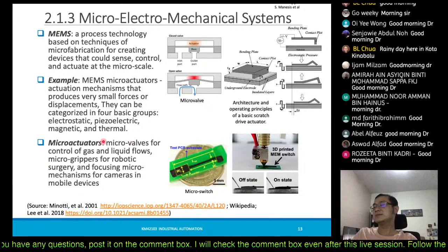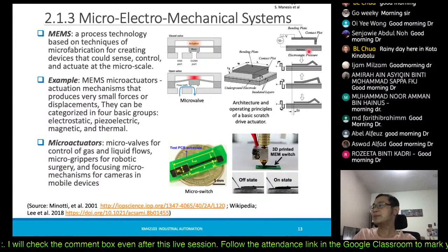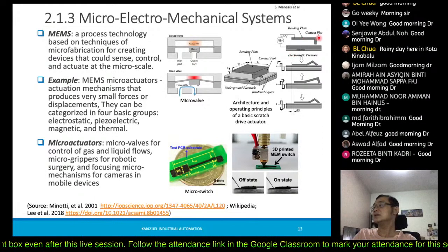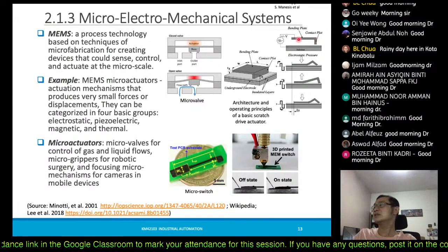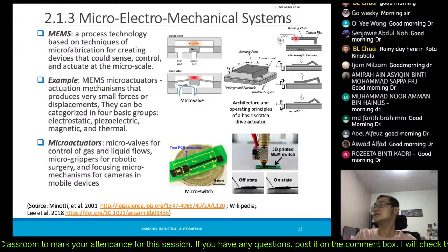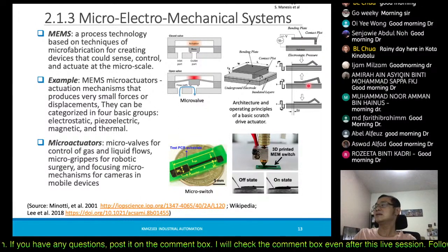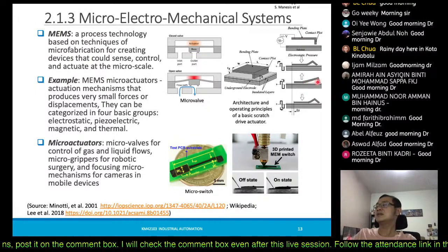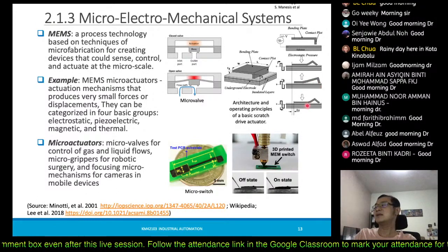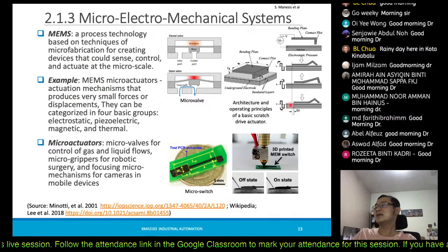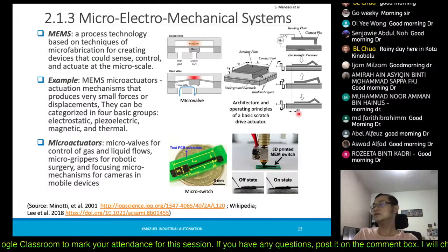So here is also a micro actuator. Here is another example of a micro actuator, where you can see that initially it is straight, then using electrostatic, this part will now stick down, then after that slowly move, and because of this movement this part will start to shift forward, and then when it releases again, you actually have moved forward a little bit, at the micro level.